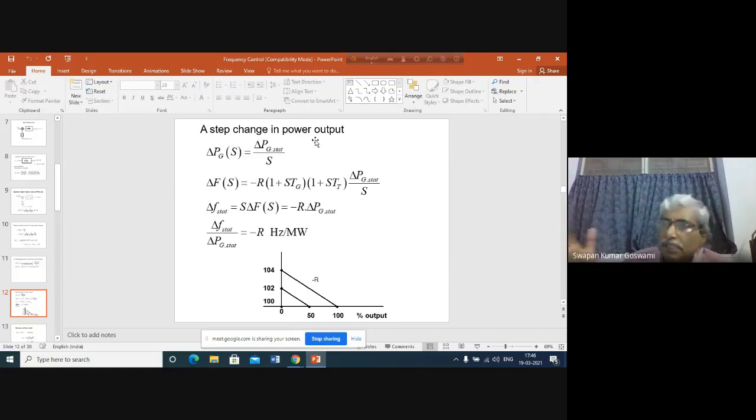So what is the nature of the load change? It is a step change again. There was no load, suddenly a load is connected by the application of a switch. So obviously there is a step change in the output of the generator. And a question may appear in your mind: the generator was delivering no power, there was very little steam flowing. What is the purpose of the steam? Obviously to rotate the rotor only and supply the no load loss only, nothing else. Now, how could the generator deliver this much power?